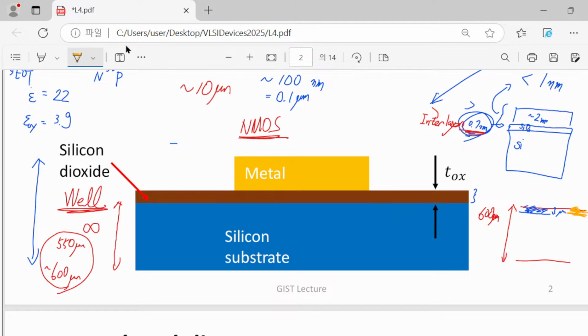If this is 600, then maybe you will have a very, very narrow region for your doping concentration. So simply speaking, we are using just the surface of our entire silicon wafer. Then maybe you can ask me this question: are we wasting the wafer? Are we wasting the silicon? Yes, frankly speaking, yes, but the thickness of a wafer is determined as 600 micrometer, not by its electrical property.